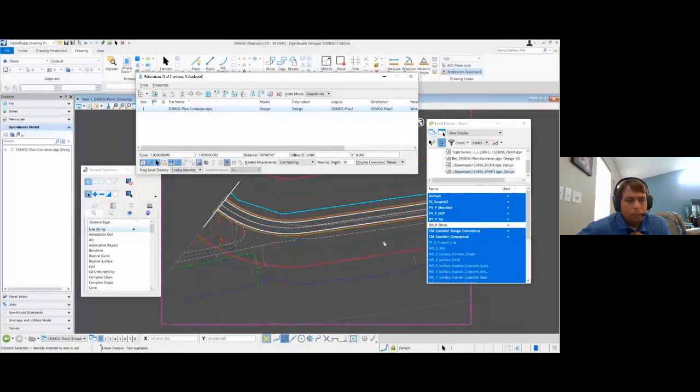And the caveat here is there's no way to override that like there is with display overrides. That is an all or nothing kind of thing. You can't have one drawing model be different from the other ones because that variable is controlled for the entire configuration. You can't turn it off per file, per model.